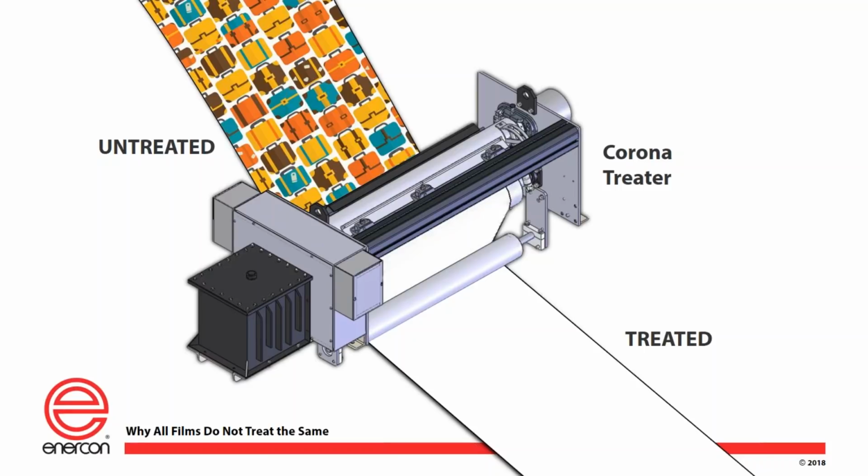They can be fillers, surfactants, colorants, flame retardants, anti-stats. There's just almost an endless array of different things that can be on the surface of those films. Some of those things are very benign. They don't affect the material going through the treater whatsoever. Other things can be quite important to the success of treatment and may require you to operate the treater in a different way.